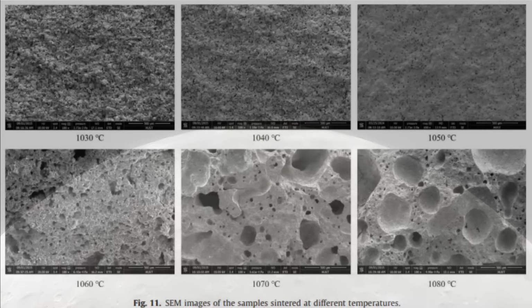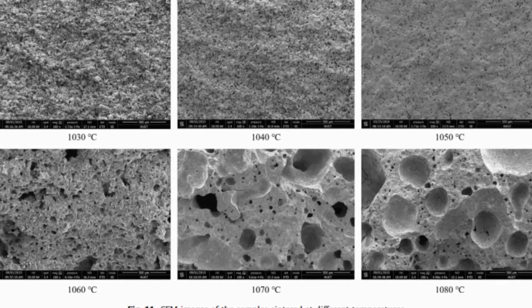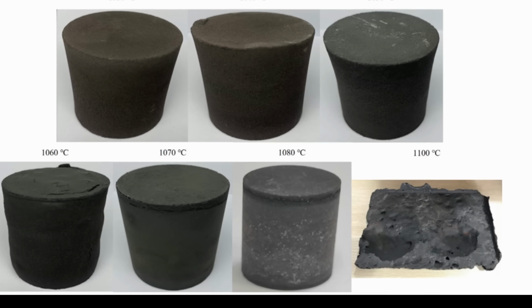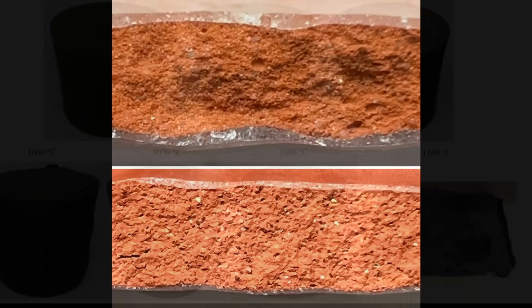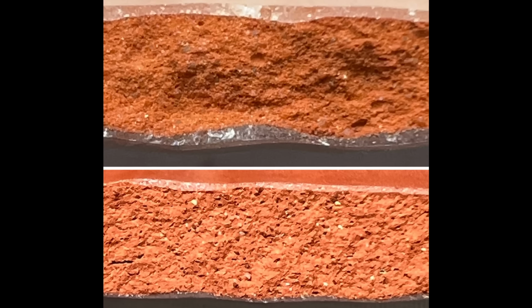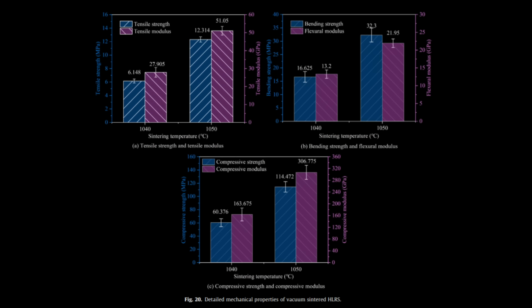We talk about sintered regolith a lot on this channel. So why cast it? What advantages does casting have over sintering regolith? Well, sintered regolith is more like a ceramic. So think of tile or terracotta. Sintering requires about half as much energy to produce as cast regolith, and it's stiffer, but it doesn't have as much compressive and tensile strength.